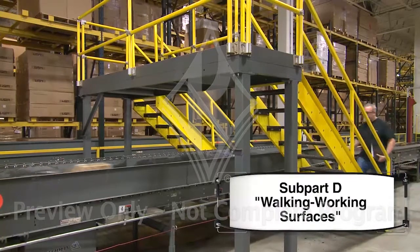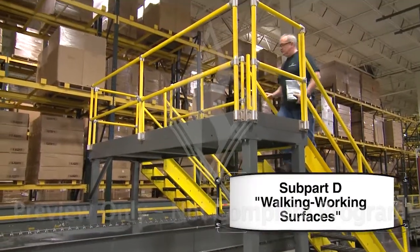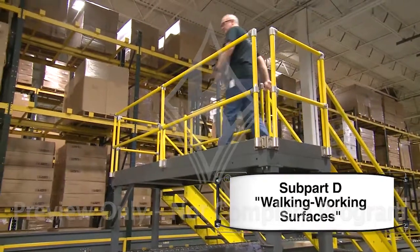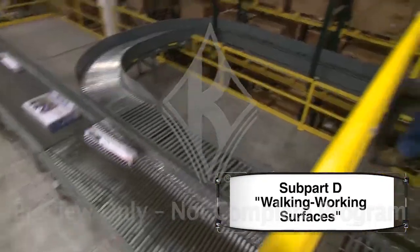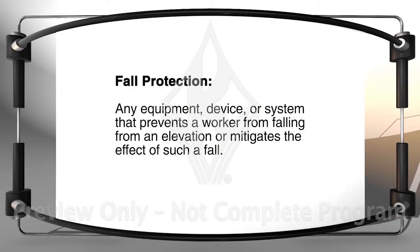Because of this, OSHA requires the use of fall protection when working 4 feet or more above a lower level in all general industry workplaces under Subpart D, walking working surfaces. OSHA defines fall protection as any equipment, device, or system that prevents a worker from falling from an elevation or mitigates the effect of such a fall.